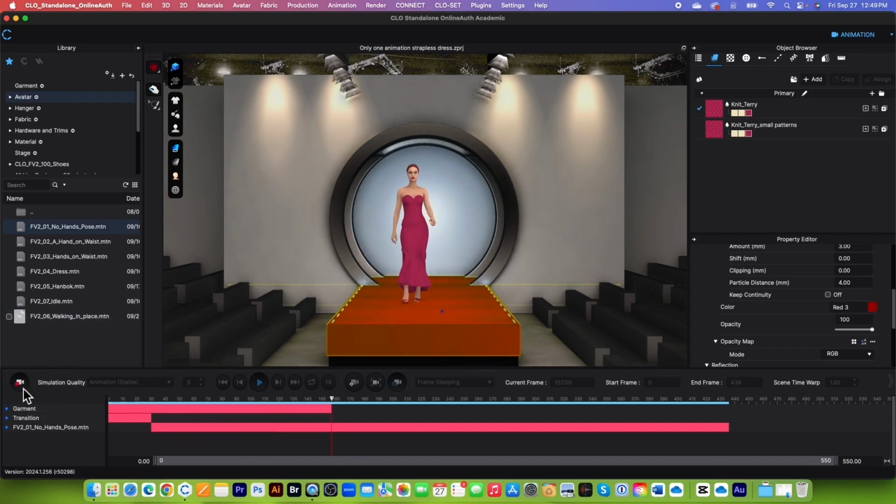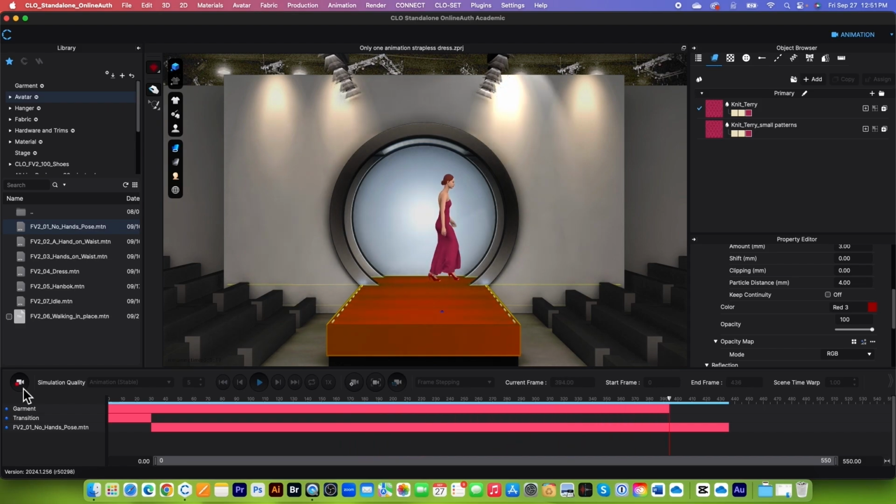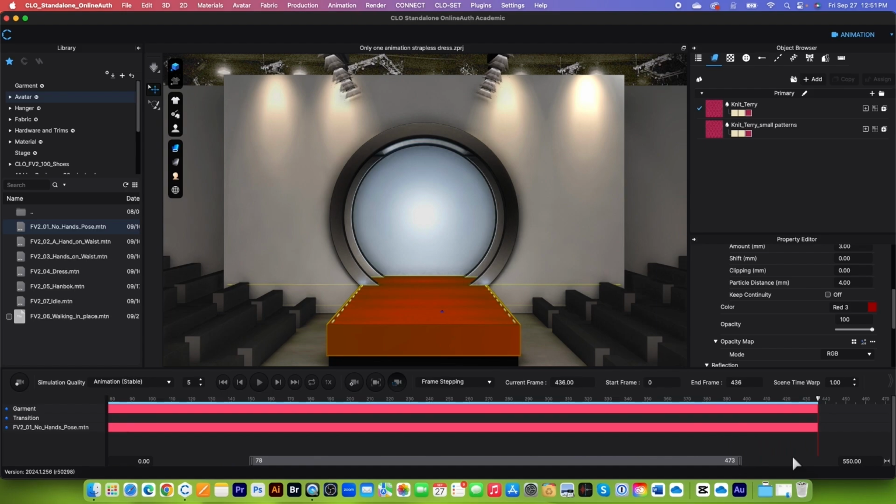I will speed up this process, guys, to save us some time. So I can see right here now the playhead has reached the end frame. If you first open your animation and you don't see this entire full bar here, be sure this number here is bigger than this end frame. For example, I have 550. I can have as low as 500 and then press Return or Enter on the keyboard. So I can still see this end frame here.